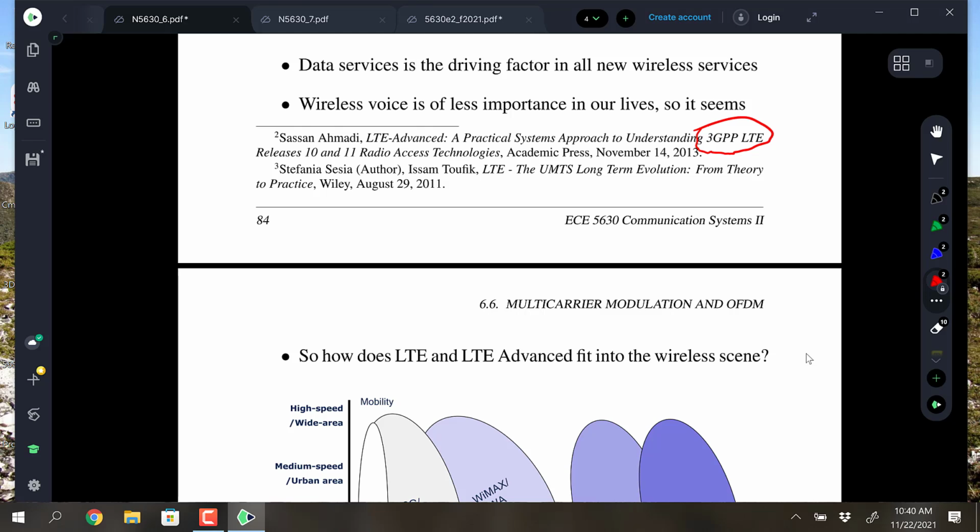Yeah, we now have, I don't know how many radios we have on our handsets, but I think it's at least 5, but I'm not positive. It's several, yeah. It's a lot. I mean, we have a GPS with multiple correlators. We still have to support GSM, I'm sure. We have to support OFDM, CDMA for some networks. And then LTE and Wi-Fi are different, right? Yeah, Wi-Fi is another radio. And then we have 2 radios there because we have the 2.4 and the 5. So it's at least 5 radios, I think.